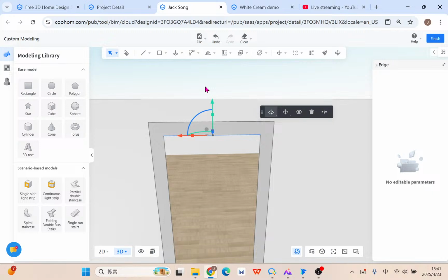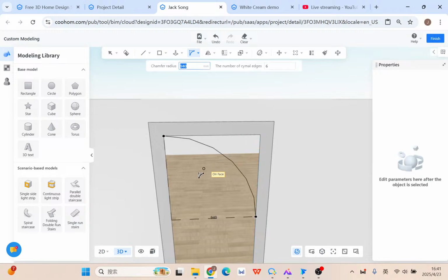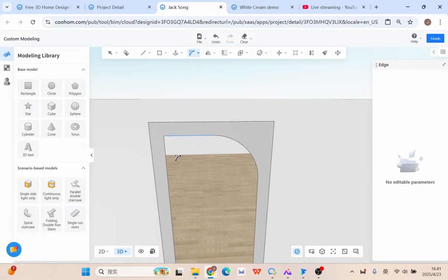At this moment, what you need to do is use the Boolean 2D, holding down the shift button, but of course not the entire length. Number 35, the edges, chamfer half of it. Here you can see it automatically gets a midpoint. Here as well, midpoint.